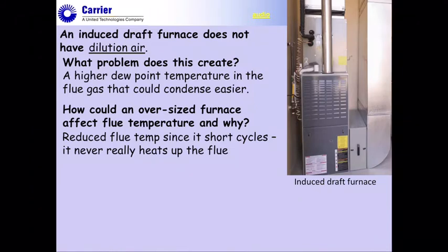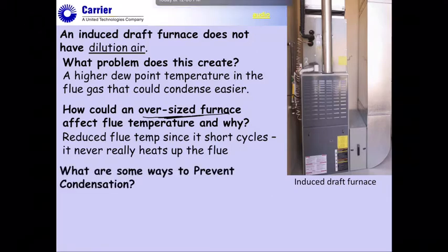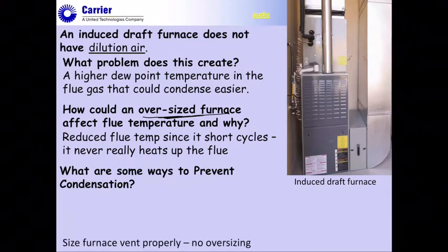If the unit is short cycling, it never really heats up the flue. On an oversized furnace, you never really get a chance. The unit runs, it heats up the building super fast, and it shuts off. You never get a chance to sustain any temperatures. So again, the runtime has created a problem with this.